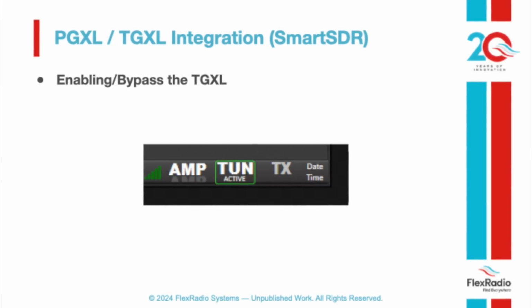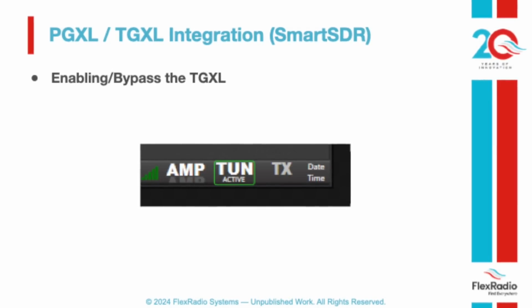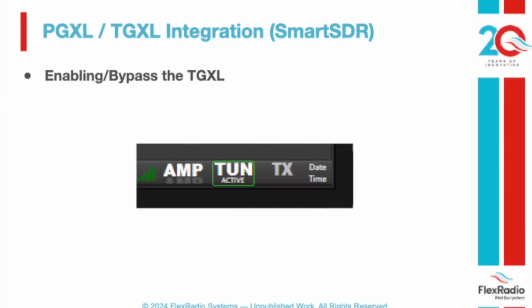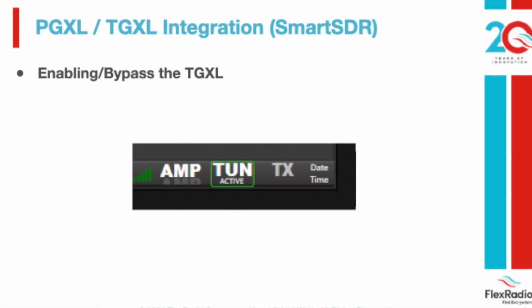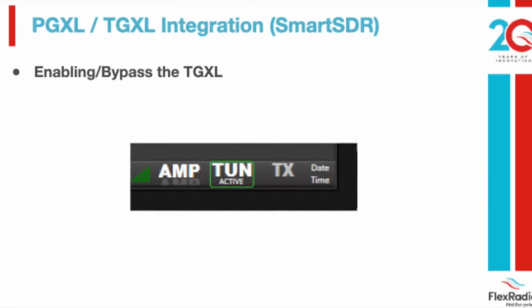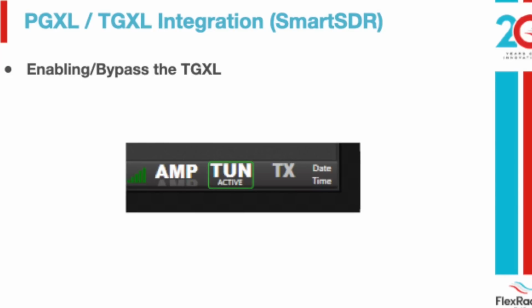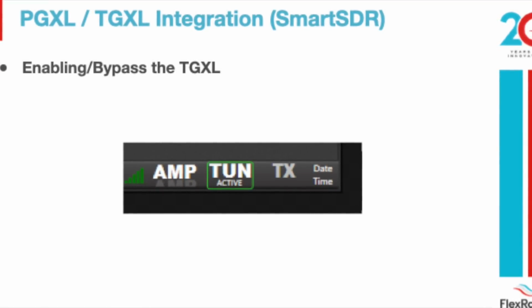So across the top is the forward power, and then you've got the SWR. The forward power goes up to 2,000 watts, SWR up to 3. And then you have the 3 settings for the pi filter. So you've got the CLC settings that you can see there, and you can also drive those and click the bypass to bypass it if you want. There's a tuning indicator down here that's now next to the amp indicator, so when the tuner's active, it'll light up like this.